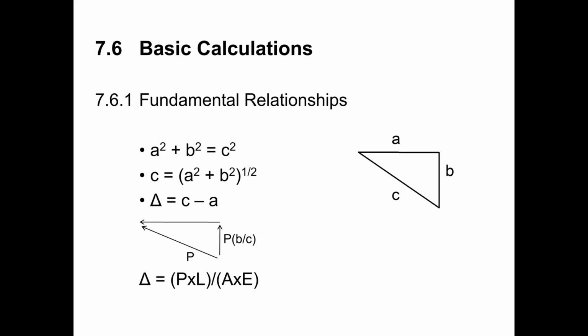So we're going to tension the strand straight to 24,000 pounds. Then we're going to push it down into the draped position. It's going to gain 6,000 pounds when we do that, so that once everything is complete, the strand has 30,000 pounds of force in it. Okay, so that's the second calculation we're going to do.